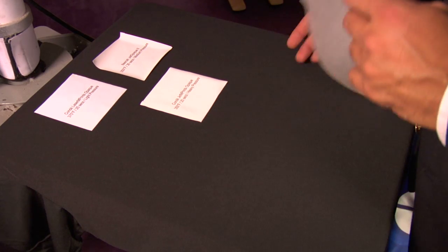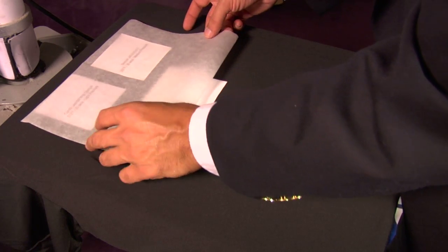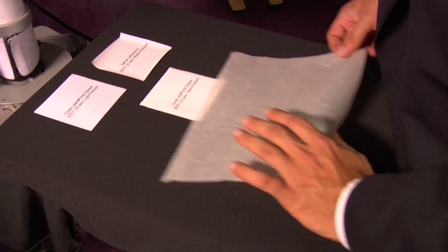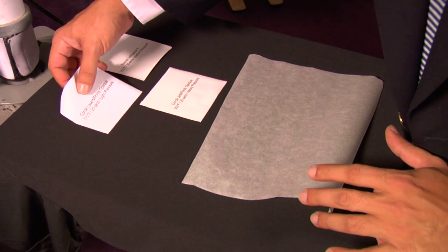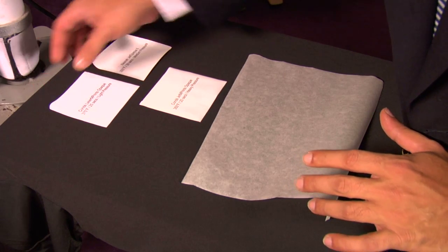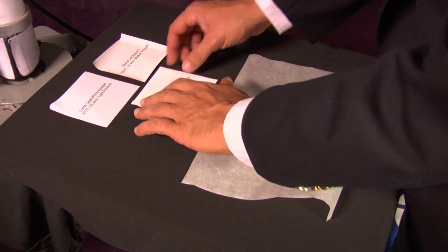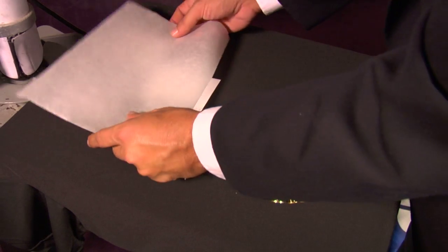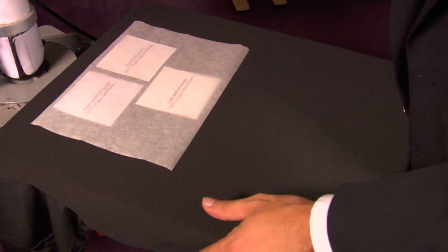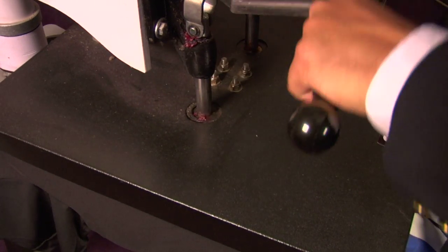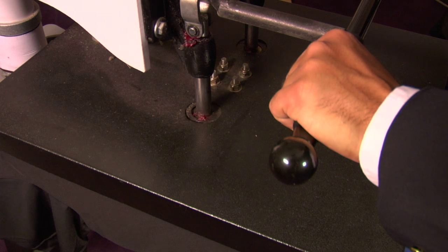Next, we'll cover the material with our silicone sheet or non-stick sheet, making sure that we completely cover the material so that this opaque material does not stick to our heat press. Here we go. Now, we'll swing our heat press over, lock it into position, and use the time, temperature, and pressure settings recommended for the opaque material. Make sure you consult with your opaque material for those instructions.